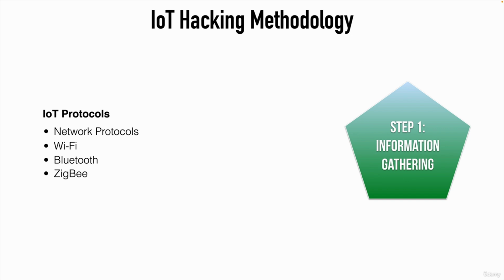We also have the Zigbee protocol. Although this isn't new, it's been around for more than a decade, in fact. It is an alternative used in place of Wi-Fi or Bluetooth for some low-powered IoT devices. In fact, many smart light bulbs use the Zigbee protocol as opposed to the point-to-point connectivity of Bluetooth. That's because Zigbee operates in a mesh network that allows it to communicate with multiple devices and to scale very easily. There's also Z-Wave, another wireless protocol that's been around for quite some time.